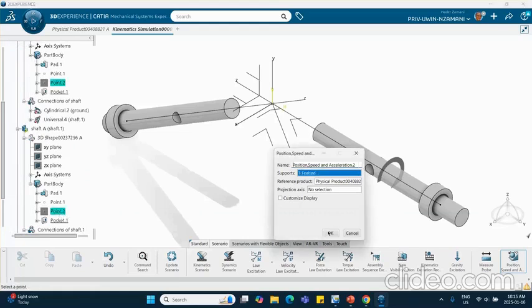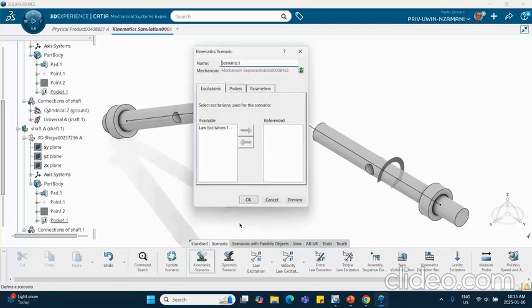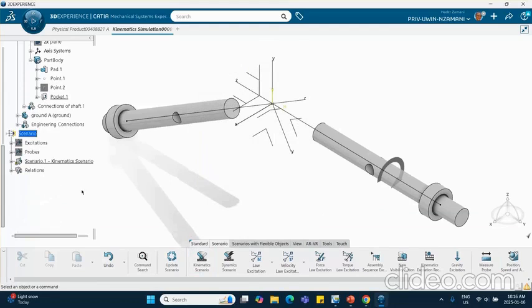That fellow. So okay. And now we go and do a kinematic scenario. This is the law of excitation over a 3-second interval. Let's do a 3-second interval and make this thing smaller, 0.01. And for the probe, these two, one of them is for the driver, the other is the driven shaft. Say okay. And now we're going to run it.